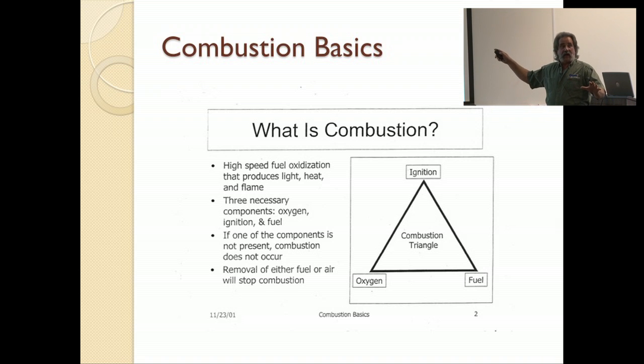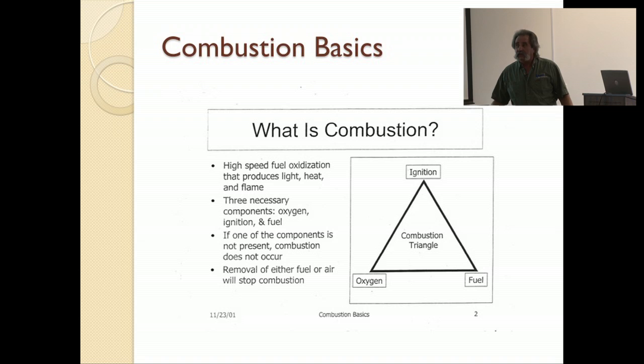So stop. If it doesn't fire, what am I missing here? Do I have oxygen? Do I have fuel? Do I have ignition? It's one of those three that's not occurring.